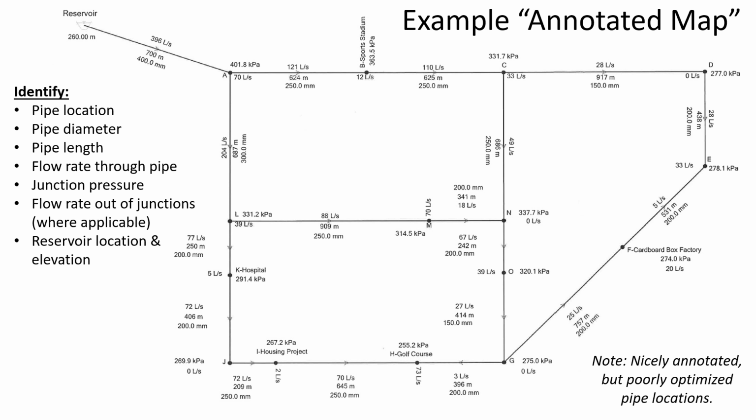And then the other map that you upload is, you have to go back into the junctions, turn off all the demands, and then show me how the system is performing under static conditions when there's no demand. So what's the maximum pressure under 0 demand, and then what's the minimum pressure under the design condition. And so then that will illustrate the system's performance under the 2 extremes it's likely to encounter.